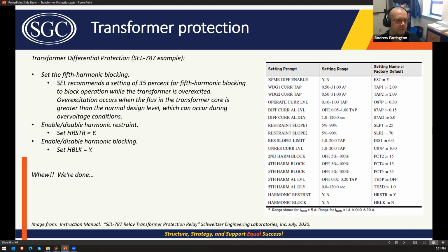You said it was when it was initially energized. No, it had run for 10 years, and then just one of those times, because it needed 2 out of 3 blocking, the GE relay only had a 1 out of 3, and the Schweitzer blocked it, but the GE didn't, because it needed 2 out of 3, and the second phase was just below the 20%. I think the setting was.